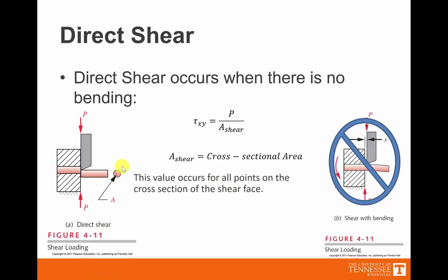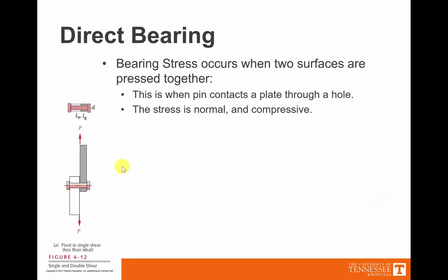So that's shear. Bearing stress is what happens when you pin something together. That's the most common case for it to happen. It's compressive, so what we're trying to do now is squash this piece of material. So here's two pieces that have a pin running through them, and the formula is the force that we're using to try to pull these parts divided by the area of the bearing.